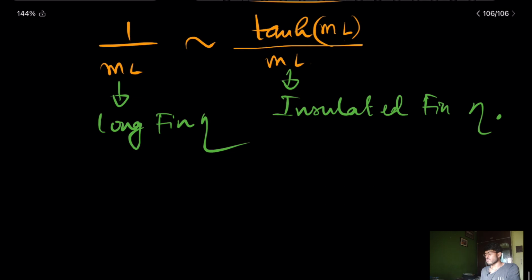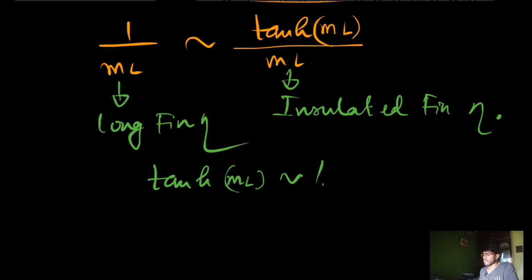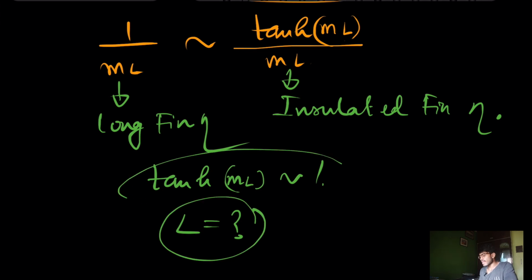So by that, if you compare this also, then you see my tanh ml should be of the order of 1. So you have to find for what value of L my tanh ml is of the order of 1. So for that also you can consider the fin to be long enough. So you have to compare the expressions.